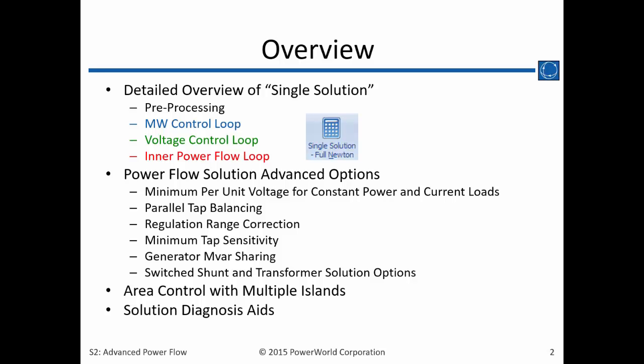We'll also talk about some advanced options for a power flow solution and how you can set up the options in Simulator to adjust what your power flow solution does. There are also some area control topics that we'll talk about with multiple islands, and some solution diagnosis aids for when you're looking at a power flow solution and trying to figure out what it's doing, or why it might not be solving, and what you can do.